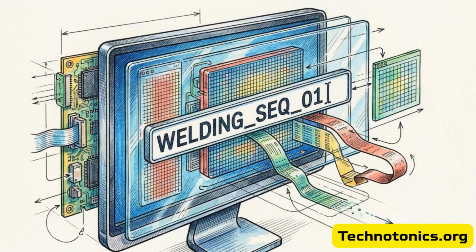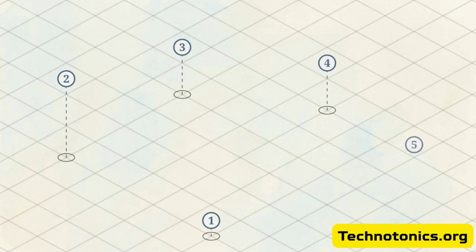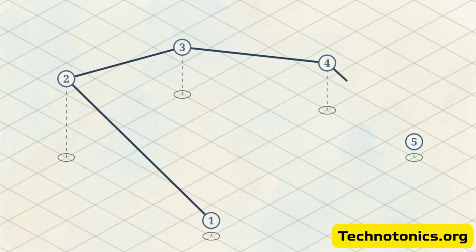We create a new program file and name it to reflect the specific mechanical task it controls. This diagram shows how we define the robot's physical movements. By clicking specific waypoints, we build a trajectory sequentially connecting multiple target nodes in 3D space. We then dictate the specific movement speed the robot must maintain as it travels between these established waypoints.